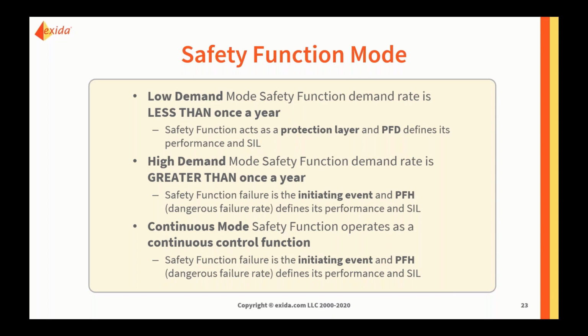And either that translates directly into our accident frequency if we get no additional benefit from any follow-up protection layers, or can be somewhat reduced with follow-up protection layers that would prevent the hazard, or prevent the failure of that safety function from leading to the accident consequences in most cases. So those different roles of our safety function need to be considered properly in layer of protection analysis.